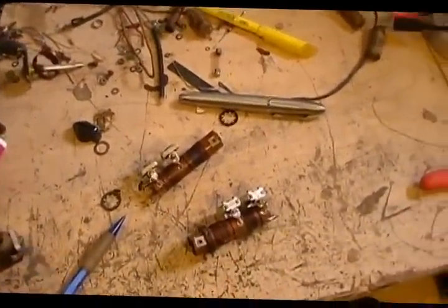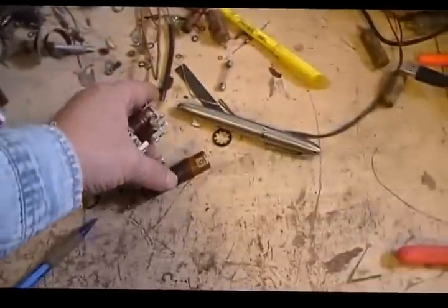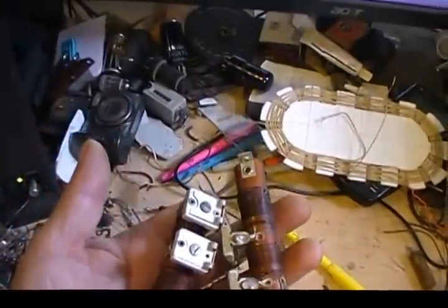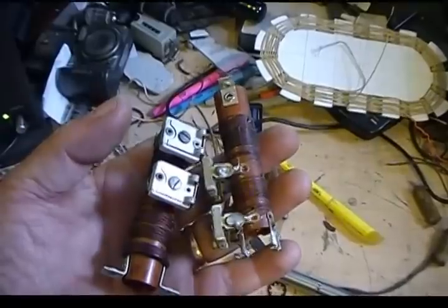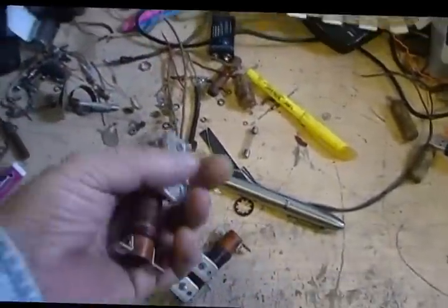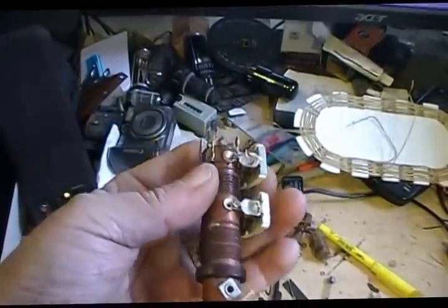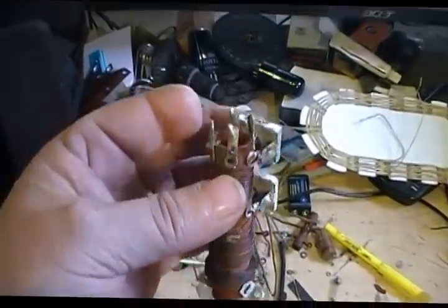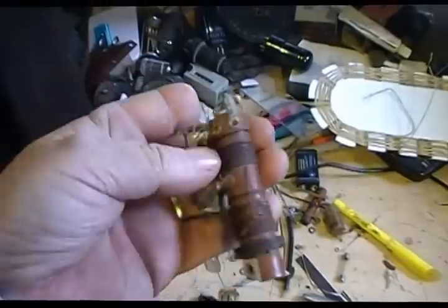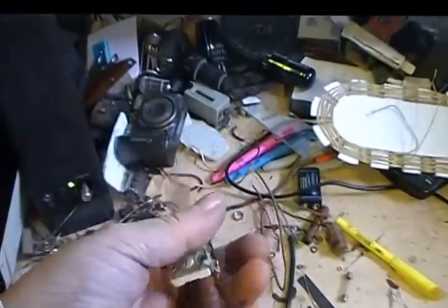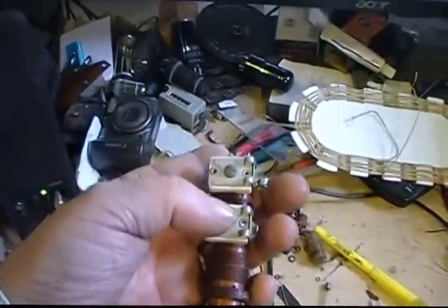But if you do get in that trouble, then the first thing to do is establish which coil is which, and you tell that by the number of windings. Oscillator coil always has the least number of windings on it for each band. Secondly, look for common points, if there's any. A lot of coils will have them. They won't be individualized out to the different windings where you have a whole bunch of points. Look for those common points. Look for other things that can help you, like these have got condensers on them, caps on them.